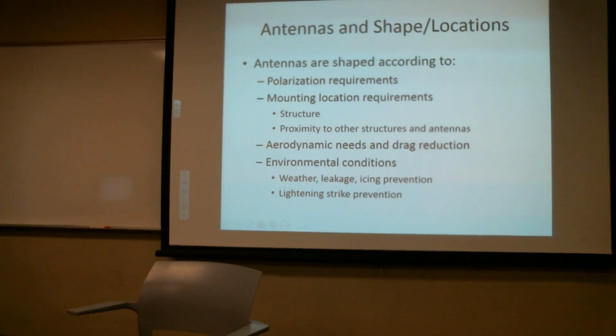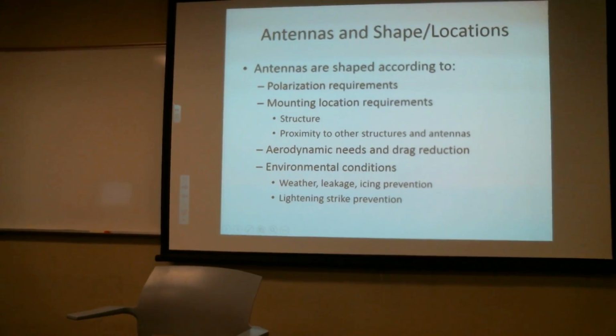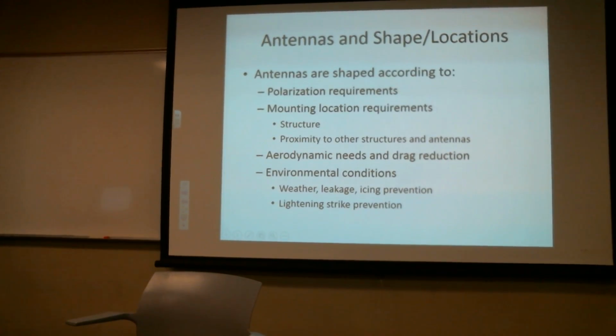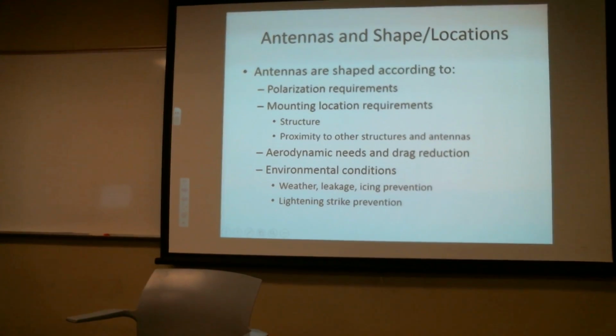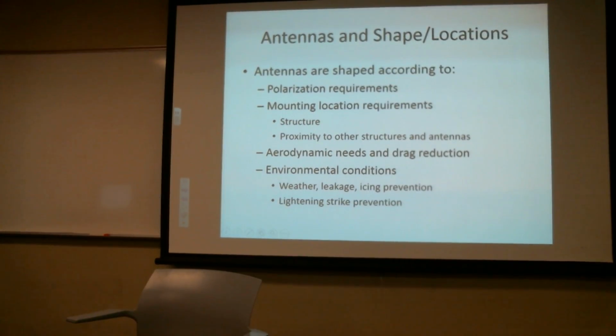The ones going this way, you'll never have a problem. But I'm going to have to be pretty careful about other structures. Well, one of the things you have to bear in mind is one of the structures that doesn't look like a structure while the airplane's sitting on the ground is the propeller. The propeller, when it's spinning, acts like a big metal wall that's 72 inches in diameter, or 76 inches in diameter. As far as electromagnetic radiation is concerned, it's just a big round metal disc. So it's not going to penetrate through it very well.